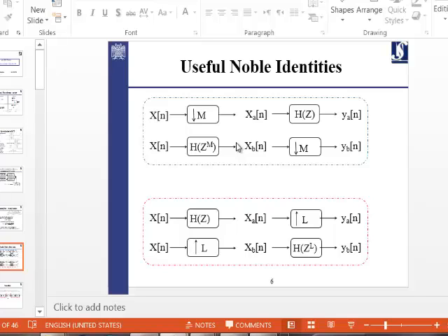So if you do the m minus 1 zero padding and then do the downsampling, the results of these two are identical. I think you got it. So here you have the filter called h of z, assuming that the filter is like this.